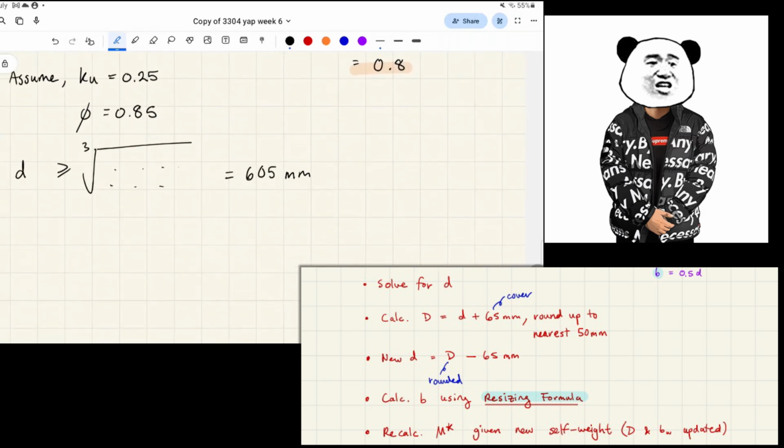But basically now here's where it gets a little bit designery, a little bit consultant-y, because it's kind of stupid. We need to adjust D, big D, the total depth, that was previously 800 mil. We need to adjust that number, and so what we do is we say that it's equal to that value d plus the total cover, which we always assume is 65 mil.